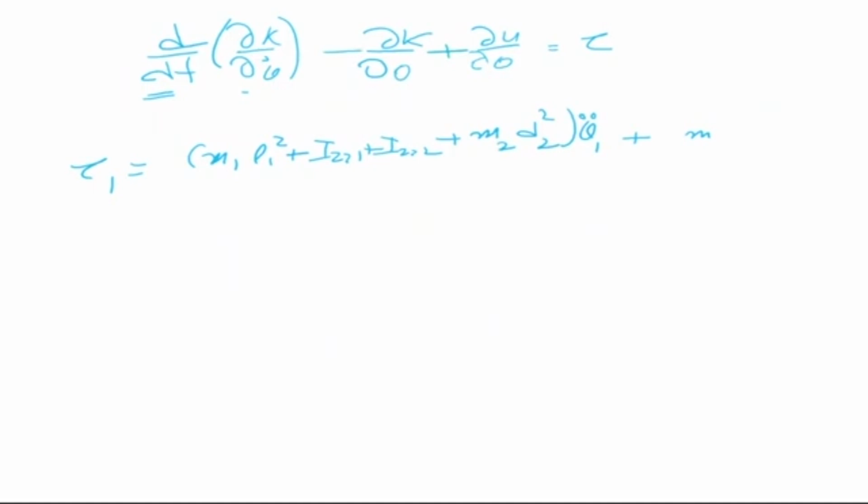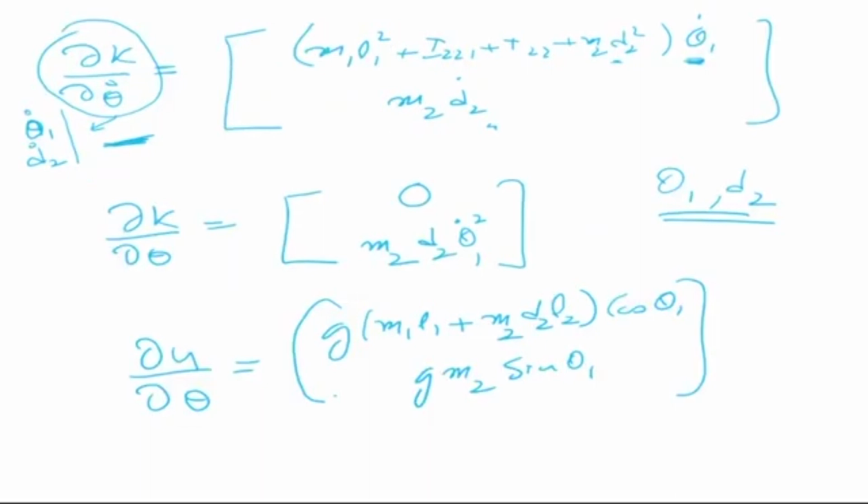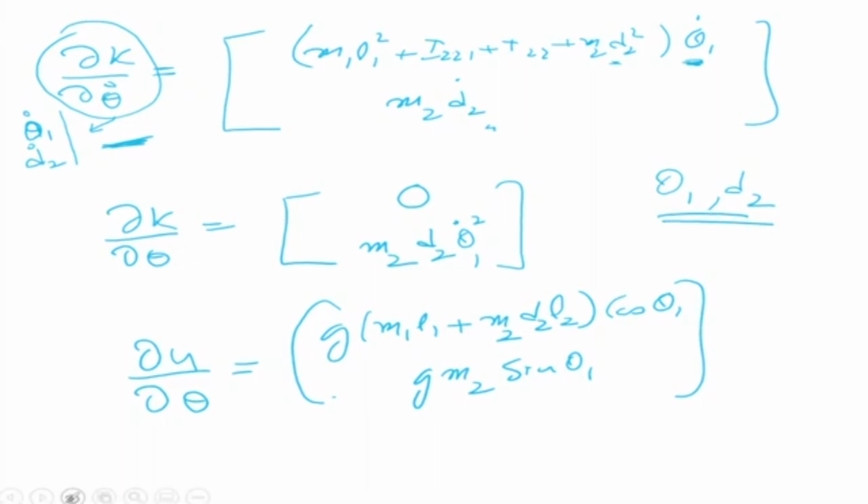So let us stop here today, and we'll continue in the next class with another example of Newton-Euler, and we'll also look at examples of Lagrangian-Euler. Lagrangian-Euler is good to implement in MATLAB because most of it is matrix multiplications, and hence it is sometimes preferred over Newton-Euler. Newton-Euler is essentially vector based, whereas Lagrangian-Euler is basically matrix based because half m v squared is there.